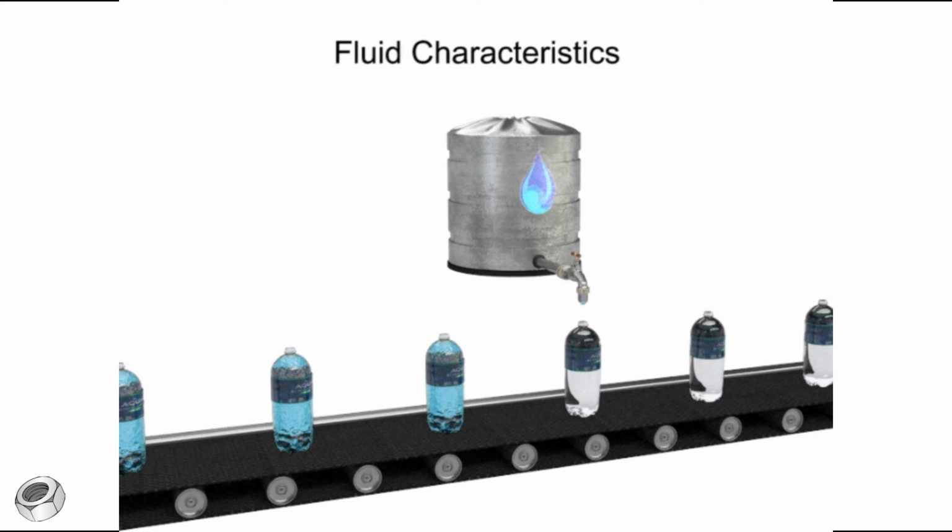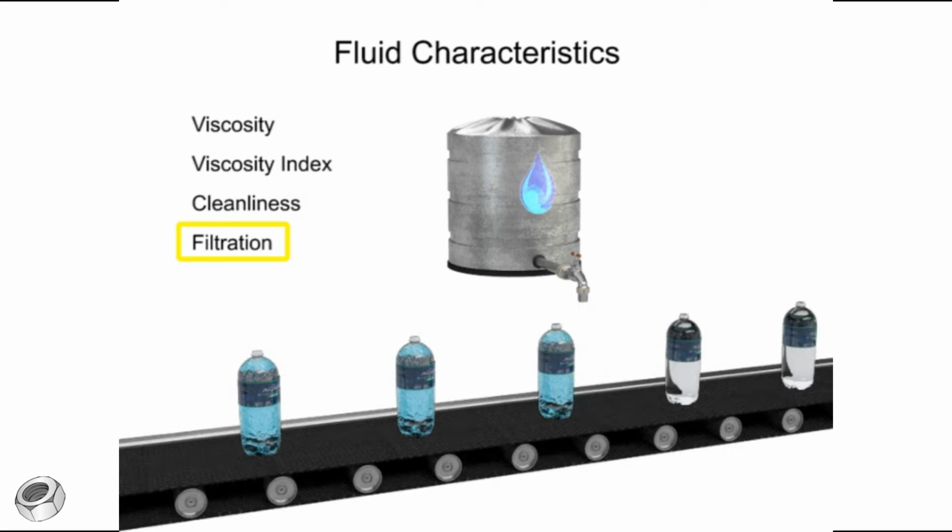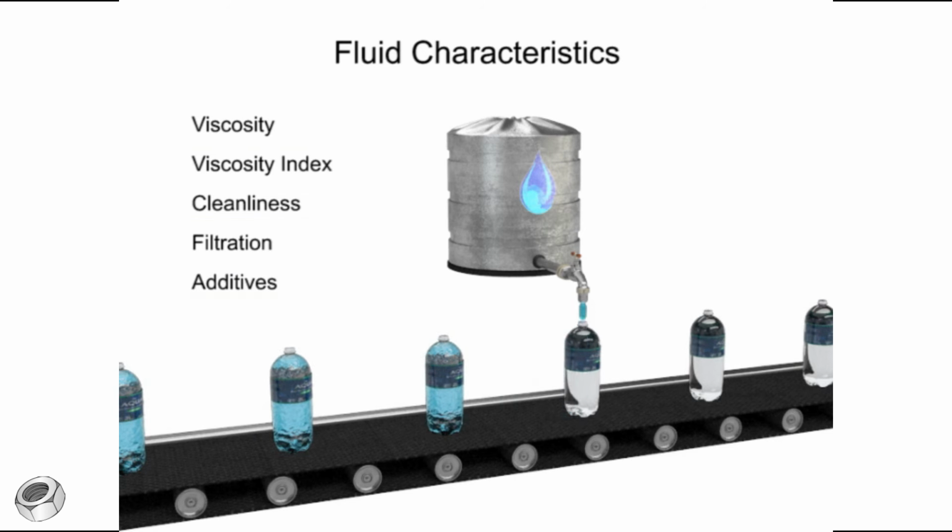The choice of modern fluids is so wide that when designing a new system, fluid characteristics such as viscosity, viscosity index, cleanliness, filtration, and additives should be considered as early as possible in the design process.